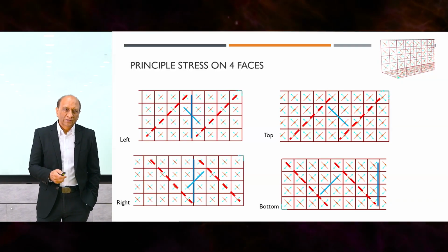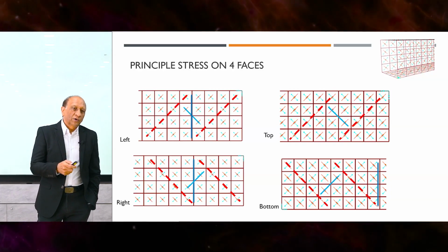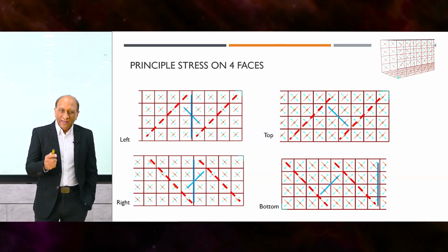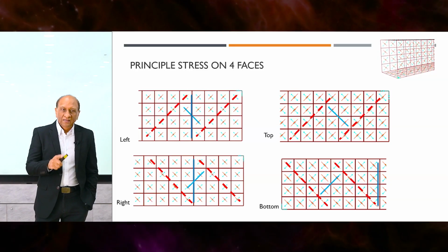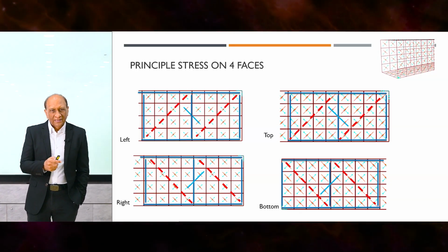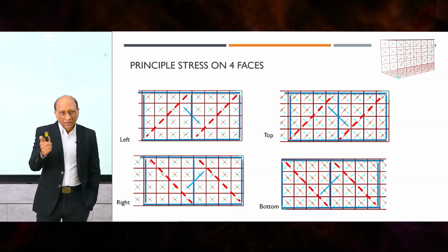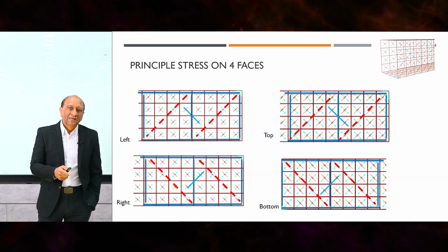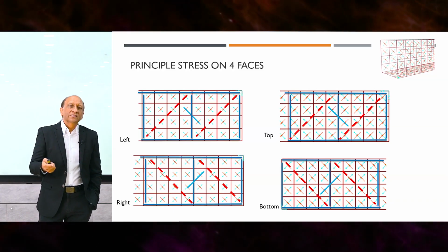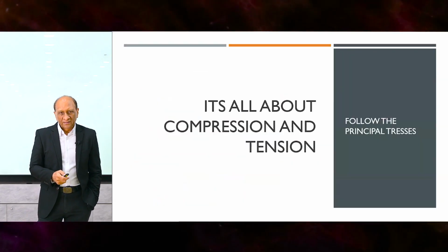The same concept is used. So it's nothing new. We are already using the concept of the strut and tie in a way in concrete design, even for shallow beams. So you get the complete picture now. And then you also get axial stresses and axial reinforcement increase because of the truss mechanism. You have A_L, the axial reinforcement increase due to torsion, coming from the truss mechanism.